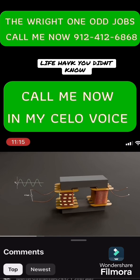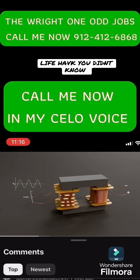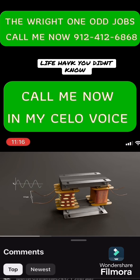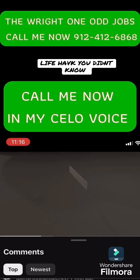As the core is also made up of conducting material, the alternating flux passing through the core induces loops of current inside the core due to electromagnetic induction. These loops of electric current are called eddy currents. Eddy currents cause energy loss inside the core in the form of heat, which reduces the efficiency of a transformer. That's why, in a transformer, a laminated core is used instead of a solid ferromagnetic core. A laminated core is made up of thin sheets of iron or steel, each coated with insulation.